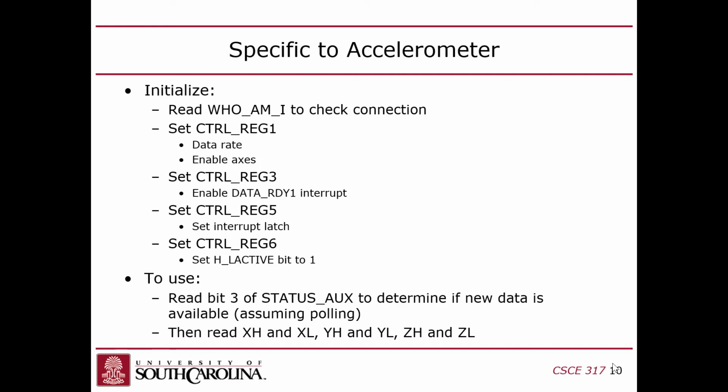How many registers are there? Well, the address of an SPI transaction is 8 bits, and 2 of those bits are used as flags. So there's only 6 bits, so there's only 64 possible addresses, and I think the accelerometer uses a subset of those, right? It's like 50 addresses. 50, yeah. So that's a lot, but yeah, most of the 64 possible.